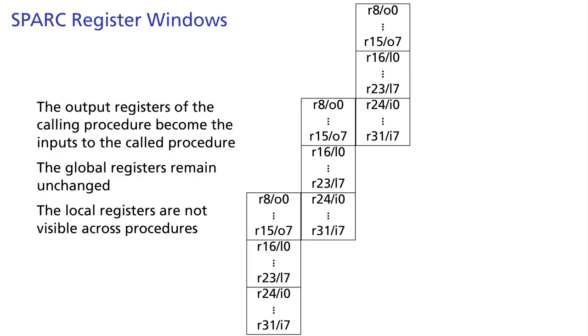Like other RISC processors, the SPARC was designed to be programmed in high-level compiled languages like C instead of manually written assembly language. RISC designers recognized that programs make an enormous number of function calls, so it made sense to make them as efficient as possible. The limited, irregular register sets of CISC processors made it difficult or impossible to pass function arguments via register. By contrast, RISC processors are designed to pass function arguments via register, and in no processor is this more obvious than it is in the SPARC.